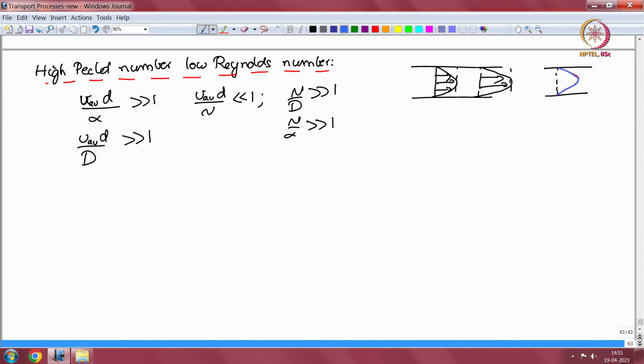If you change the pressure gradient or the pressure difference, the velocity at each point changes by that same multiple. This is true for a laminar flow. It is also true for the flow around a particle, for example, when the Reynolds number is small.